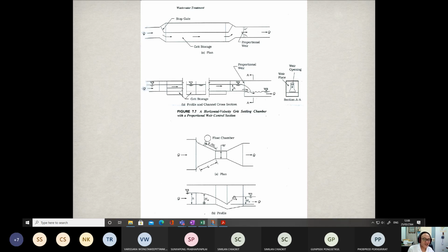At the Mahasawat water treatment plant, if you go back and have a look at the video clips, you will find the hydraulic jumps somewhere in the clips. In the clips, you will find they add the chlorine, they add the alum, and the points where they add it are the places where they create the hydraulic jumps, and they make the flumes like this. So as engineers, they have to decide what the width should be and how they can make the slopes like this to create the jumps.